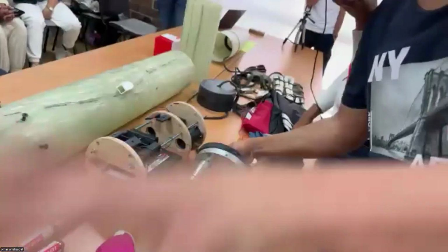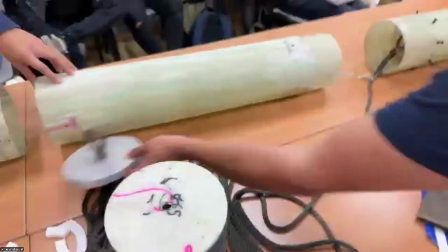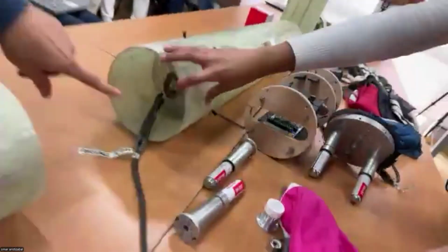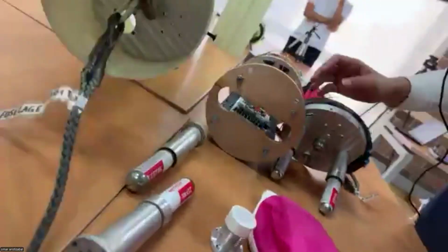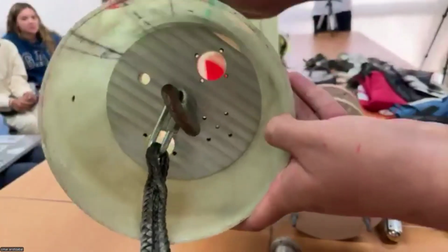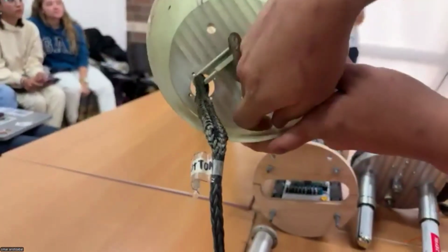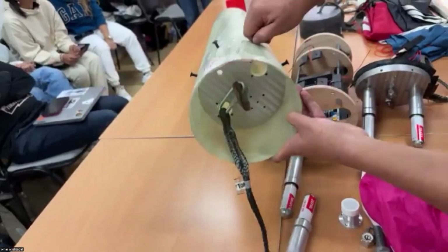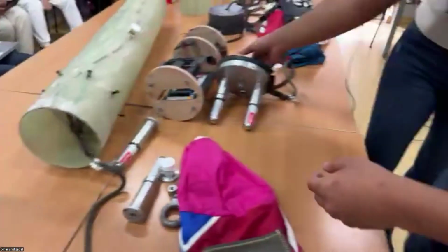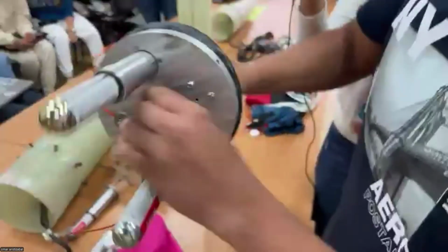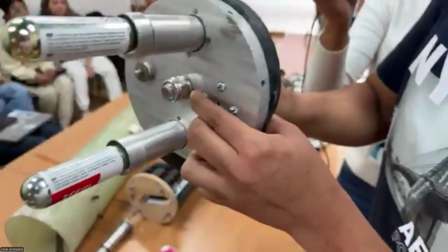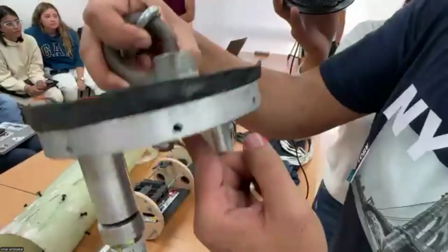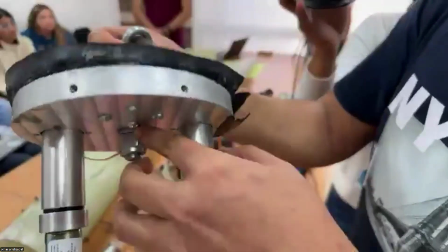These eyebolts are going to be attached to these ejection bulkheads from this fuselage section, and on the motor section, we have another recovery bulkhead located something like here. As you can see, here is one of the bulkheads already installed without the systems, so you can better see the organization of these ejection bulkheads in the rocket. These eyebolts are attached using a lock washer and a lock nut, and this bulkhead is also threaded on the inside.